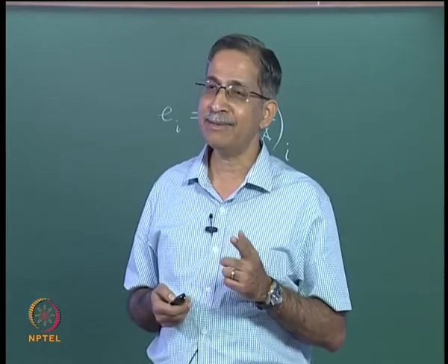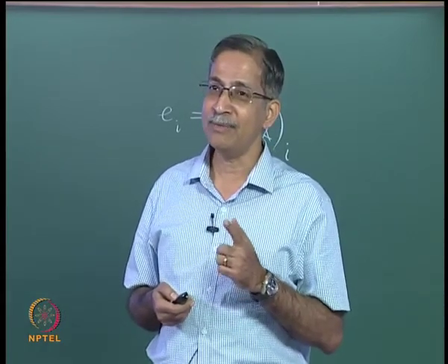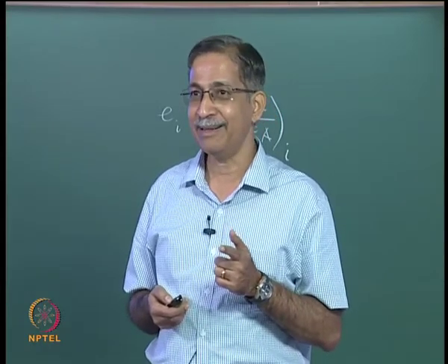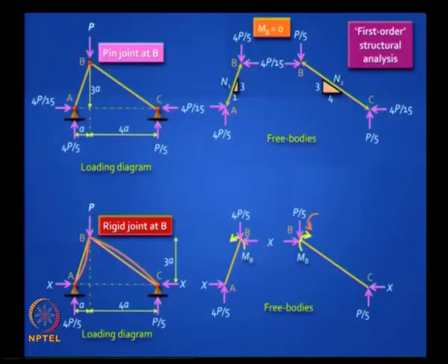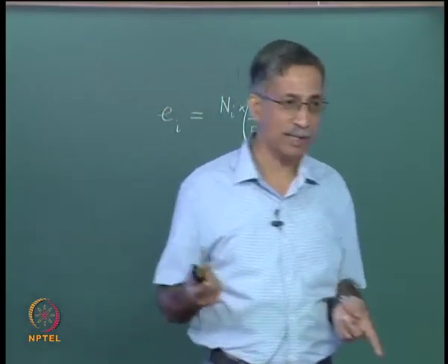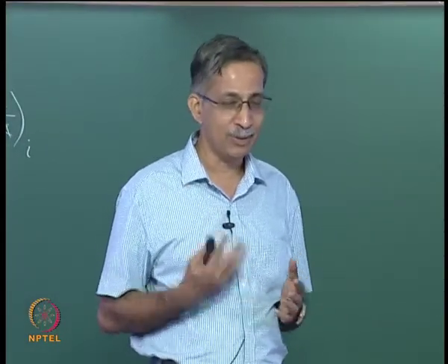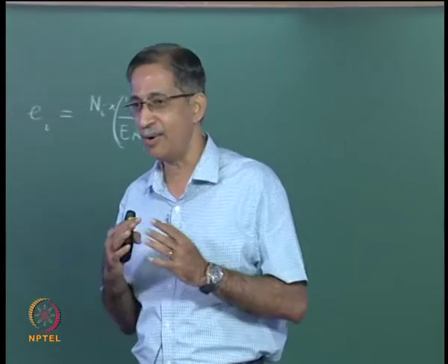So you will find that always if one of the elements is shown sagging, the other will be hogging, but your arrows will not satisfy that. So either you have to draw it like this, or you have to draw it like this, which means you will never get both sagging or both hogging. The deflected shape will not look like that. So you should know intuitively that something is wrong here.